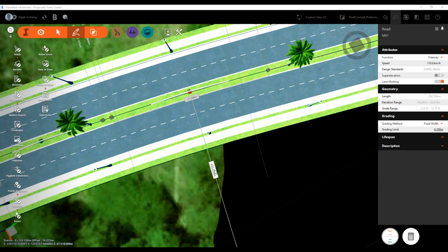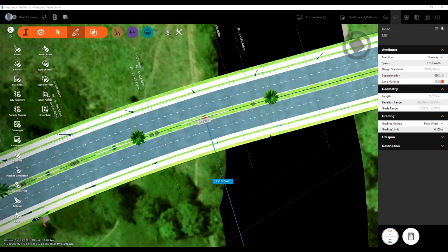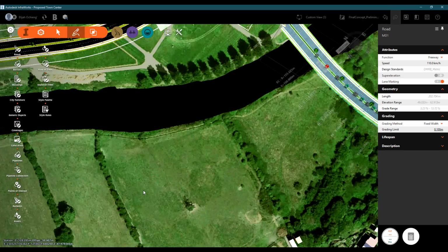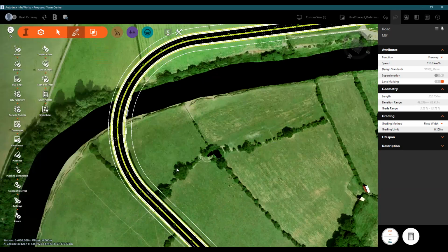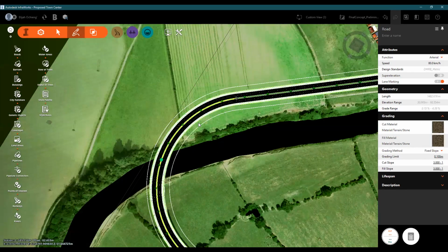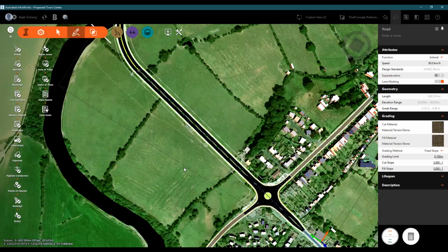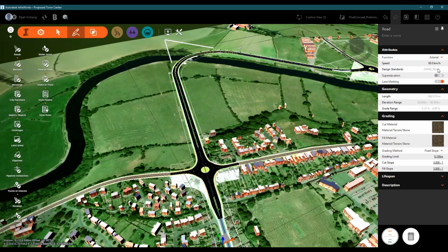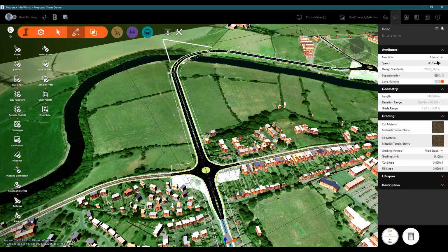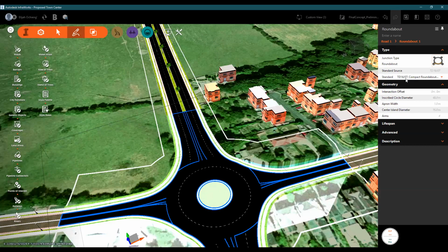As I said, the curve radius may vary based on the design criteria that you're using. So in this case, this is not depicting what I wanted to show. So I'll just switch up to the model that I already modeled here. You can see for this, my proposed concept, which I've converted into a preliminary design, I now have a very well laid out roundabout in terms of the specific design that the roundabout follows. My roundabout follows the TD16/7, and it's a compact roundabout giving me a minimum design speed of 40 miles per hour.